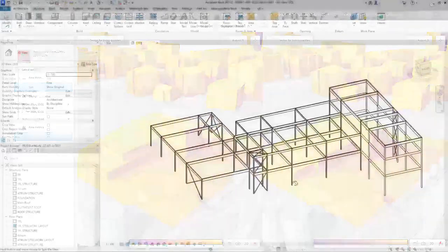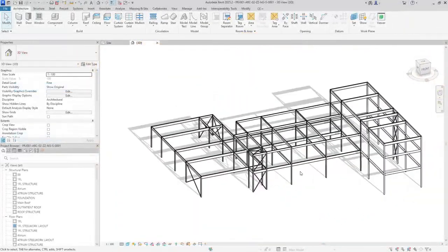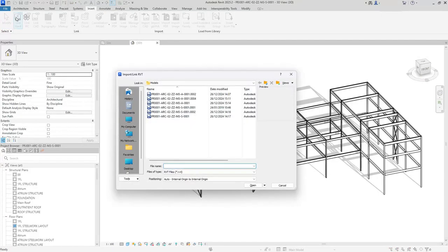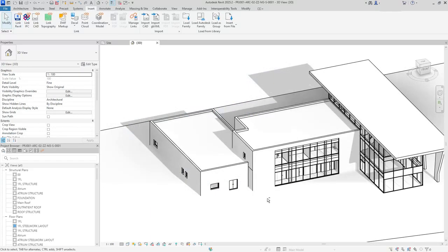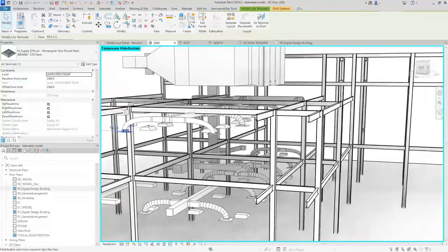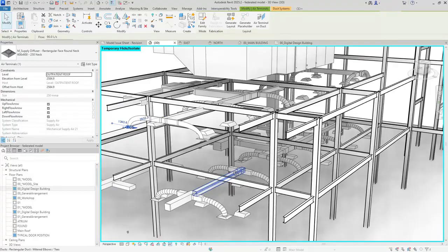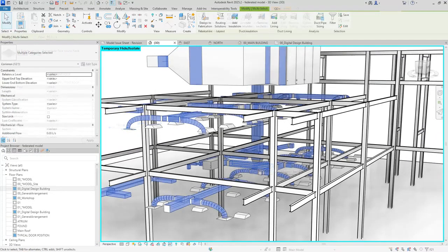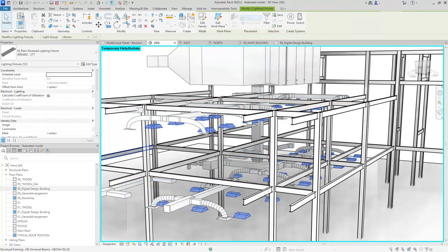Another advantage of the BIM process is the ability for teams to use other disciplines' 3D models. In a BIM project, the structural team can use the architectural model to help them design the structural model. This is called coordination. One example would be the building services team using both the architectural and structural models to design the most efficient route for air conditioning ducts, lighting and other services.